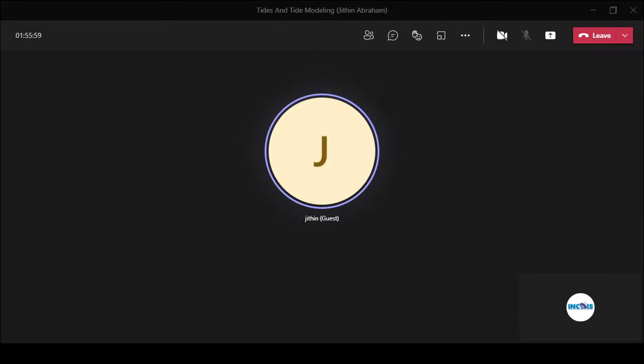Right now the accuracy of the tidal model or the satellite derived model is about 1 to 2 centimeter in the open ocean, but in near coastal areas it is lesser, maybe 4 to 5 centimeter error will be there. But it is updating yearly, I think. So in future that accuracy will be more and more with the availability of accurate satellite observation, or more observation in all coastal areas.